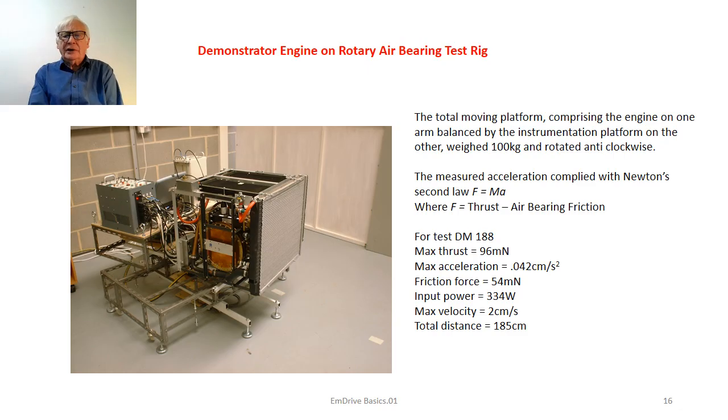Before each test run, and we did quite a few of these test runs, the actual air-bearing friction was measured by the simple method of using weights on a weight pan attached to a piece of string over a pulley wheel. I mean, very simple, but actually a very accurate way of measuring the air-bearing friction.